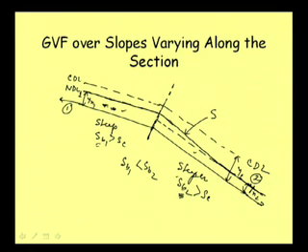We should not get confused about whether it is between critical depth and normal depth, because the normal depth here is this one, and this is of course less than the normal depth of channel reach 1, but we are talking now about channel portion 2. So, so far as channel portion 2 is concerned, this is between normal depth and critical depth, and we should always see what is happening over that particular channel portion, not on the other one. So, not here, but here. So, this is the S2 profile.